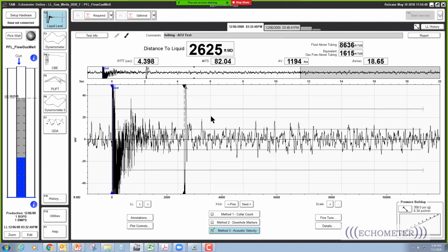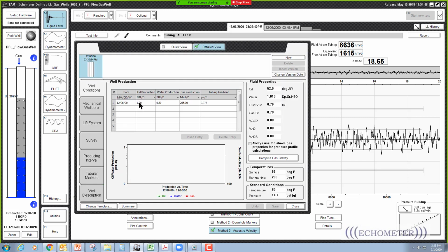This is a gas well that's liquid loaded. It's below critical rate, and this is a shot down the tubing, and the gas gun shows the tubing. The first thing that you probably wonder is why is there more condensate than water, even though the liquid volumes are the same? That's because we rounded off to the nearest whole barrel. If we click on edit and bring up the edit screen, we see that there's 1.2 barrels of oil, which means more height of the condensate and less water. It's like 40% water and 60% condensate.